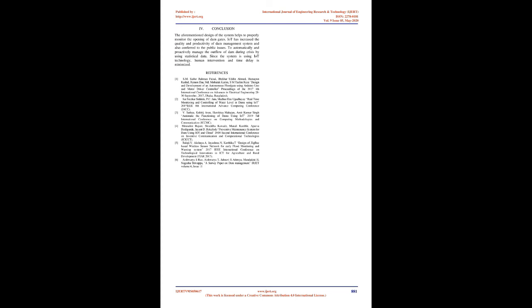3. Results. The prototype of the dam monitoring system is developed. First, the entire system is switched on and a link is developed between the network and the Raspberry Pi. The sensors take readings of the respective parameters, which are placed at different positions of the dam. Fig 4. ThingSpeak updates. Water flow sensors are placed at the dam gate exit, and the amount of water flowing out is displayed on the command window.